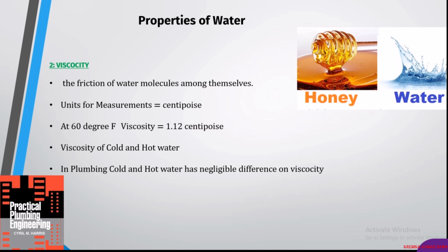But in plumbing systems, there is a significant increase in the temperature when you require hot water in your toilet or for shower purposes in your washroom. You definitely require high temperature, but that temperature is not significant enough to reduce the viscosity of your water, right? So in plumbing, if you talk about cold or hot water, the viscosity difference is negligible.